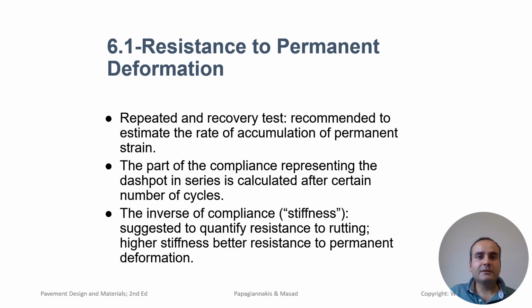In evaluating the resistance to permanent deformation, the repeated creep and recovery test is recommended to estimate the rate of accumulation of permanent strain in pavements. This test simulates repeated loading similar to what pavements experience under traffic and assesses how much permanent deformation the material